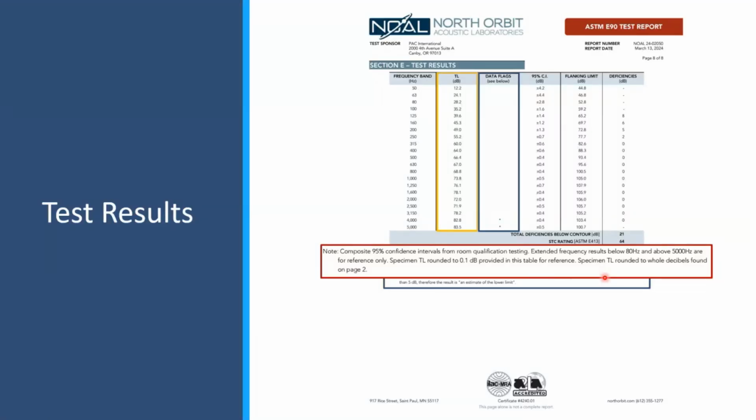And so then the lab needs to determine what the transmission loss value is of that filler wall. Because if you've got a really good window that starts to approach the transmission loss of your filler wall, again, you're going to get sound through the window, but also through the filler. And that's going to make it harder to figure out what's just coming through the window. So in that case, you would have a flag for a filler wall correction. In the stuff that PAC does, where we're building whole walls, typically we're occupying the entire opening, either for a wall or a floor ceiling assembly. So you really shouldn't see flags for filler wall corrections.